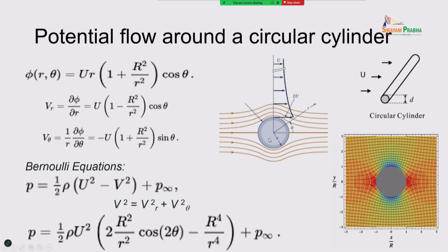Now this figure gives you a sense of the pressure, right? And there are two lines. One is a streamline, in black color. Another is the equipotential line. So the potential at this end is high and pushes the fluid to go in this direction. Now, given this pressure, we are ready to say what kind of force is in the system.